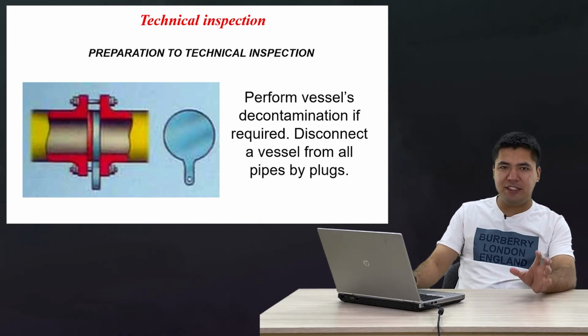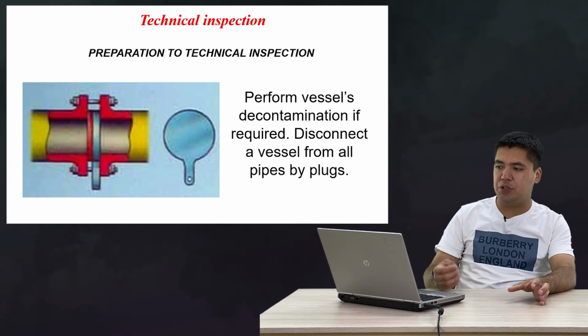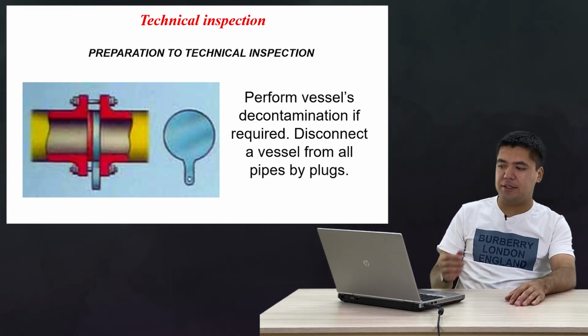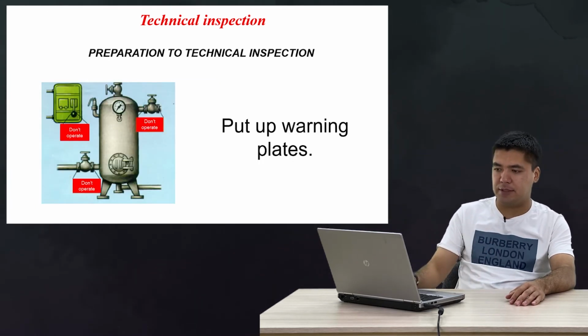Then the equipment that is going to be tested, we need to disconnect, and we need to perform vessel decontamination if required. Disconnect the vessel from all pipes by plugs. Don't forget about the plugs.